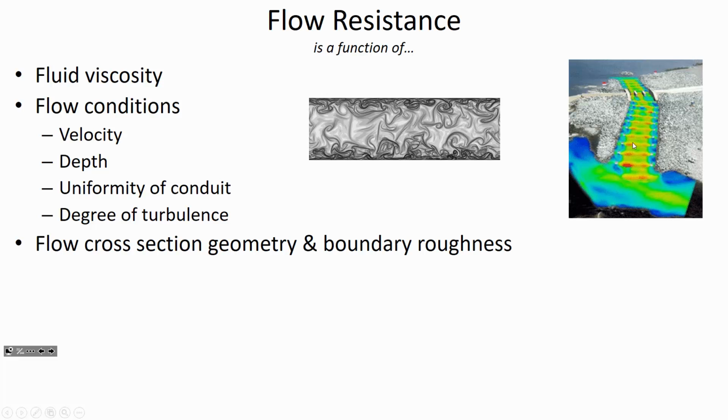It can also depend on the cross-section geometry. And just to illustrate, consider this. So let's say you have one channel that is really wide and another channel that is more rectangular in shape. Of these two channels, it's pretty clear that the top one, which is really, really wide, is going to encounter more resistance to flow, because more of the flow is close to this surface where friction is being encountered. And so, this area that's far away from any edge is going to flow without much interference from a frictional surface, whereas the furthest you can get away from a flow surface in a really wide channel like this is from the bottom to the top. And so that's what we mean by cross-section geometry, is sometimes the shape of the channel has an effect on how much resistance the flow encounters.